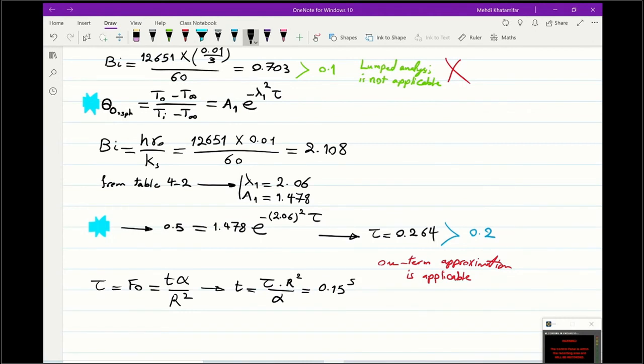Okay, so I found the time, so the height is going to be u infinity times time. So 2.1 times 0.15, which is going to be 0.313 meter. So the height of the tank must be bigger or equal to 0.313 meters to have that temperature loss from 360 to 320 Kelvin.